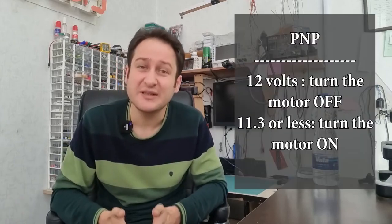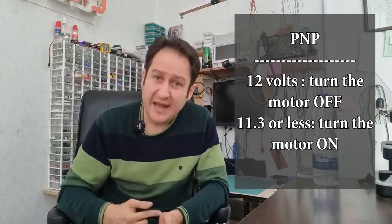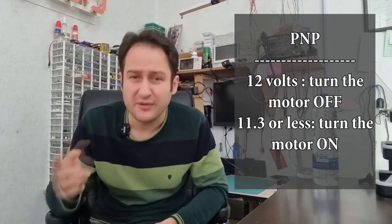But if you try to switch the motor using PNP type transistors, I have bad news for you. Because the transistor will turn on with 11.3 volts or less and will turn off with a base voltage over 11.3 volts. You can't turn the transistor off using a microcontroller, and of course you can't stop the DC motor.